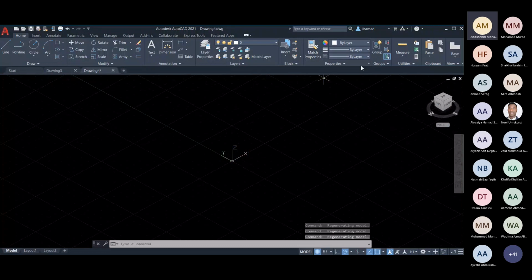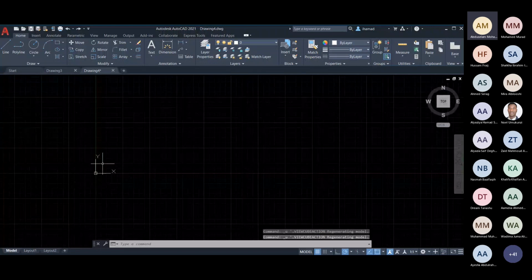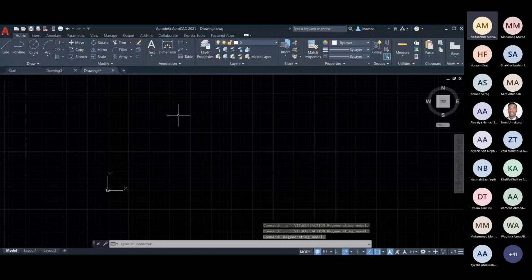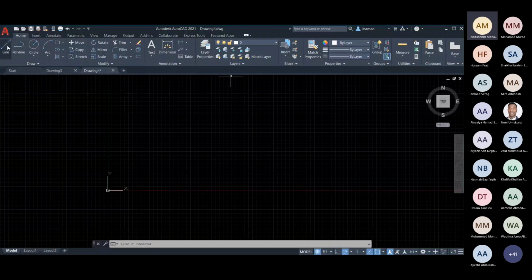Okay, so here this is our XY. So if you need to draw a line, for example, you can go to the draw menu and select line and make a line. It's very interesting here that for, let's call them ortho lines, the lines are either horizontal or vertical.